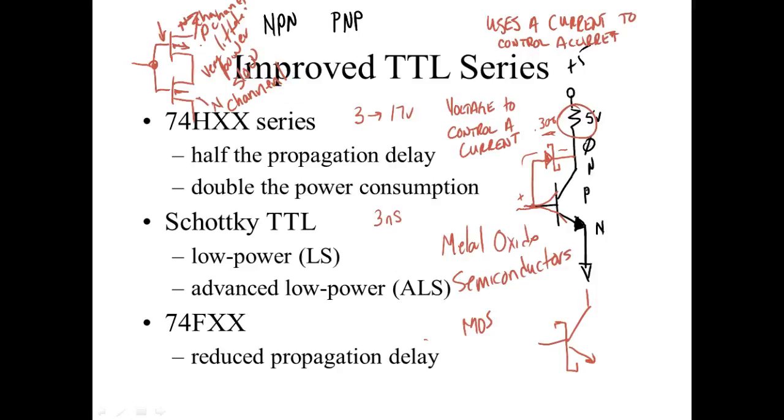If you've been around computers for a while, you understand that these computers have to be configured, and we have a section they call the CMOS. You ever heard of that term for CMOS setup? Well, you can still get into them if you know how to and change the boot sequence and stuff. Well, all it is is a little tiny piece of CMOS memory that we keep. There's a battery inside there that keeps that power on there when you turn your computer off. And that battery will hold it for about 10 years because that CMOS almost uses no current at all, right? Ever heard of CMOS memory?